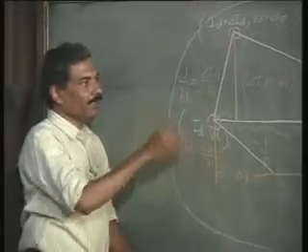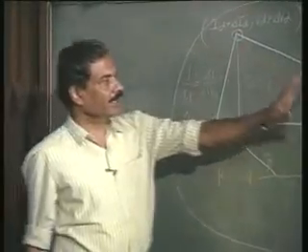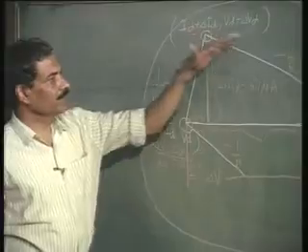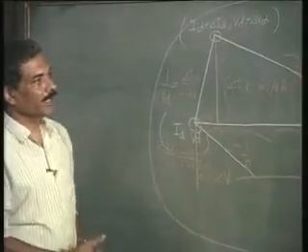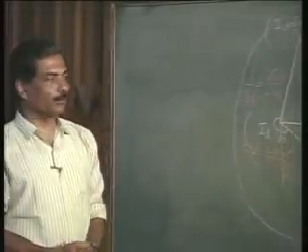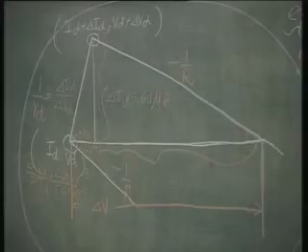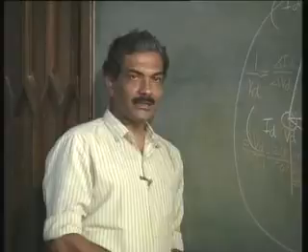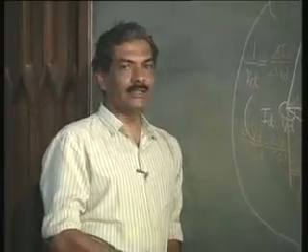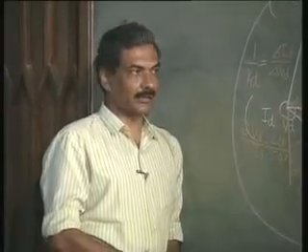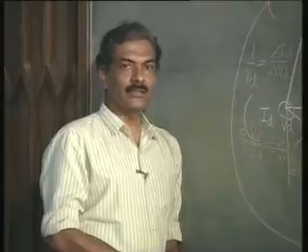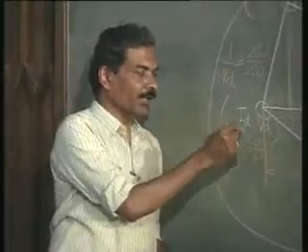Please therefore remember that all these things can also be got graphically if you really expand the characteristic around that operating point. So, what we have learned today is to represent the diode by means of its small signal equivalent, which is a resistance in the forward direction, and that resistance is dependent upon the operating point.